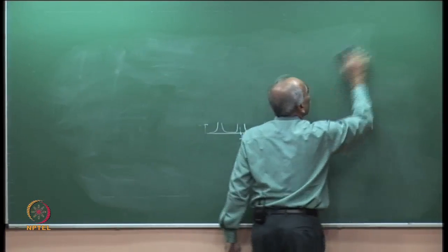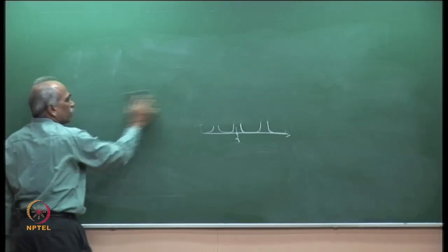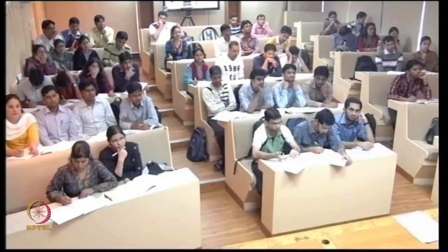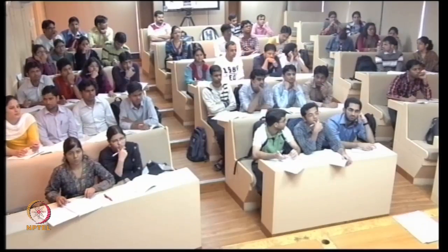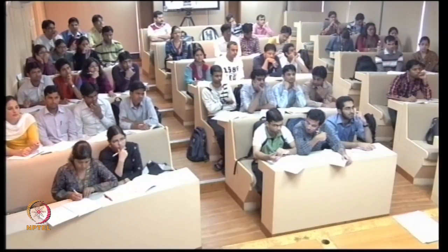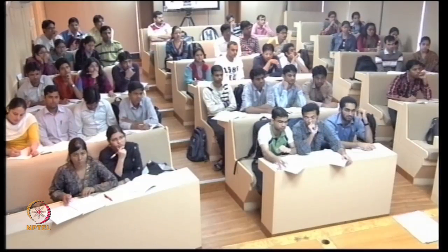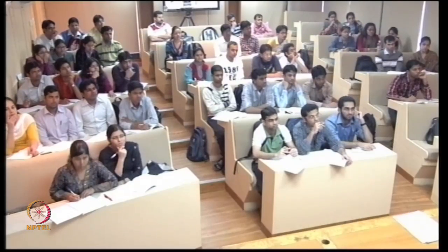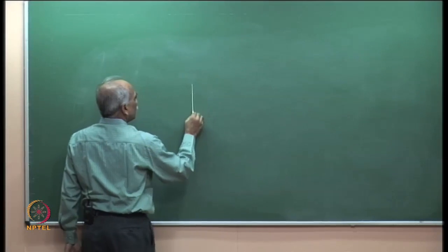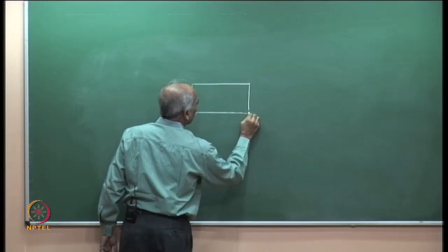So, if we see a typical data sheet, and if we understand all the technical parameters of a device, it means that we have reasonably understood the device and its operation. Otherwise, it simply means we know only the theory, we have no idea about what it is in practice. Okay. So, let me take the device package, the thermistor. You see here the monitor photodiode. What is this monitor photodiode?